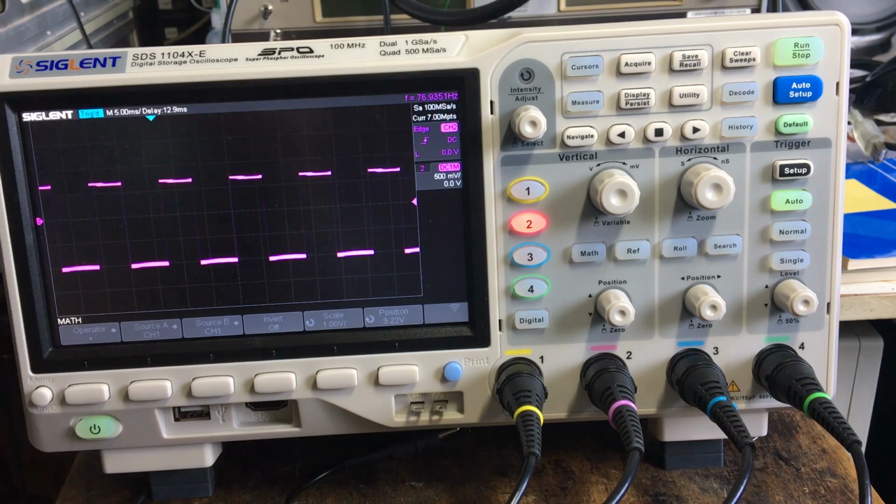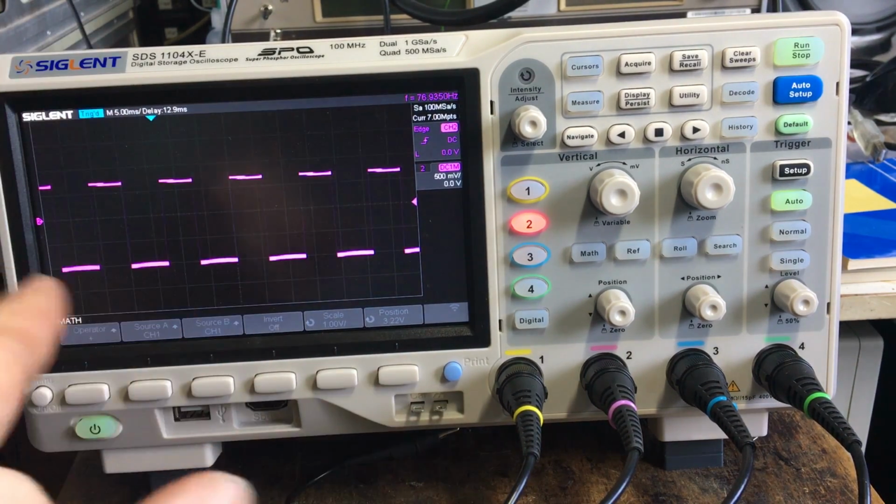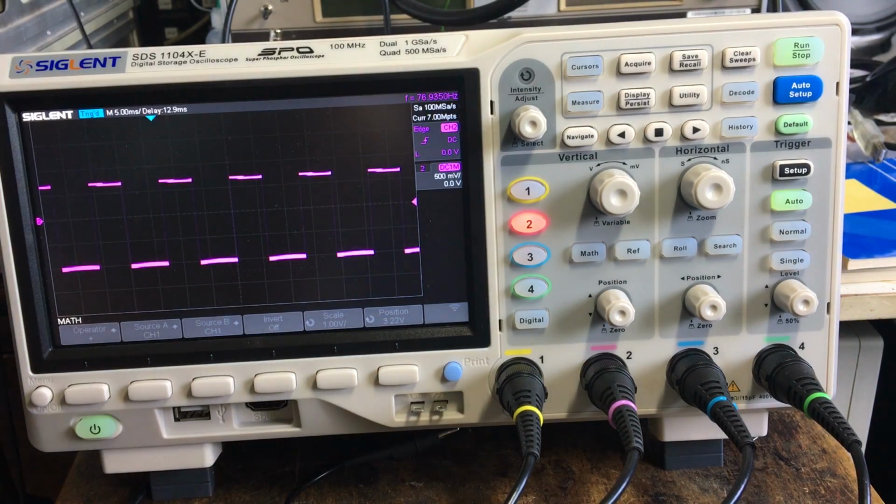Oh, what's the word? It's gone out of my head. Anyway, you can stick 2 probes onto a circuit, a positive and negative, and then do a maths calculation there to give you the final waveform. It's just a way of doing it if you can't use the earth on your probe because you've got a live chassis or there's a voltage difference or something like that.